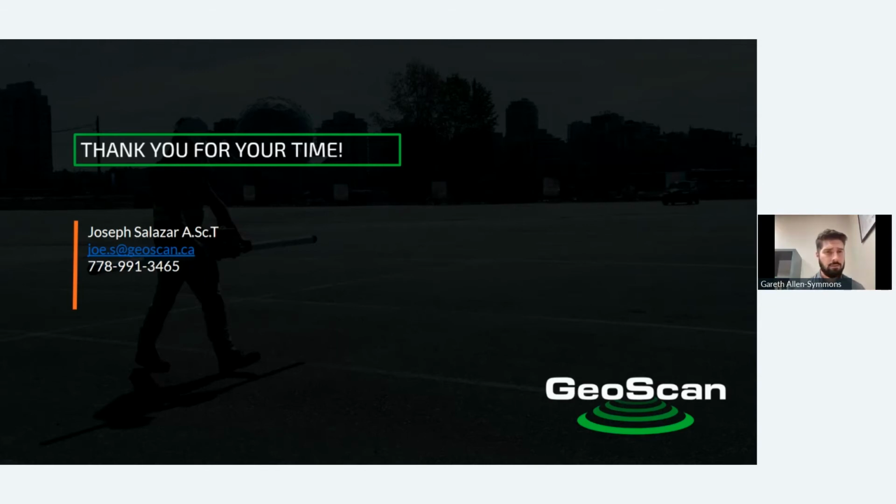Okay, and then the last one, unless there's a few more that come through, is can GPR be used to locate voids? Yes, it can. Void surveys are a great one for GPR. Again, that change in speed as the radar passes through different materials and gets reflected in the data is actually how we're able to see voids clearly. As soon as it hits the air, it just dissipates, so you can pick up that data.